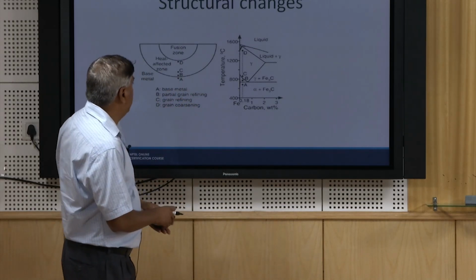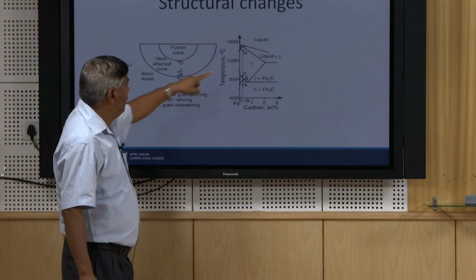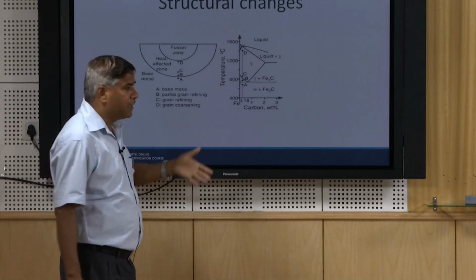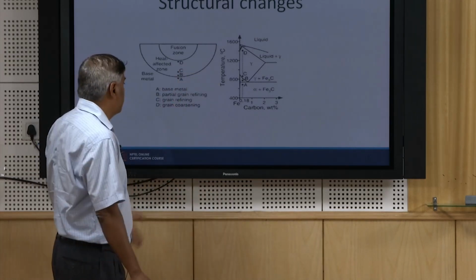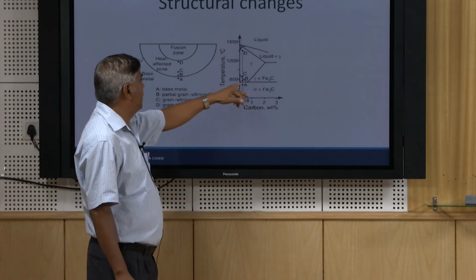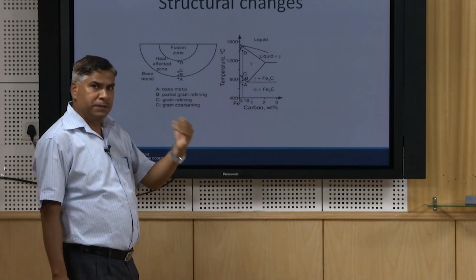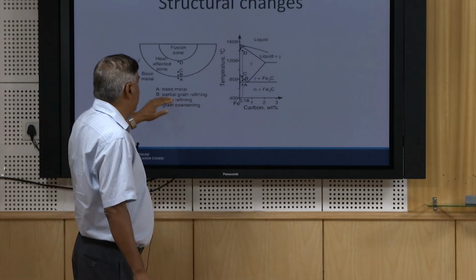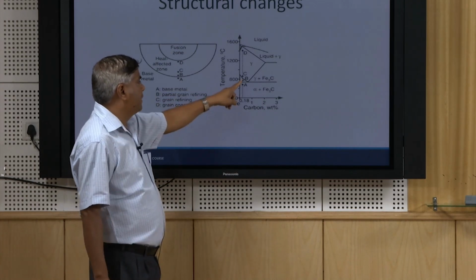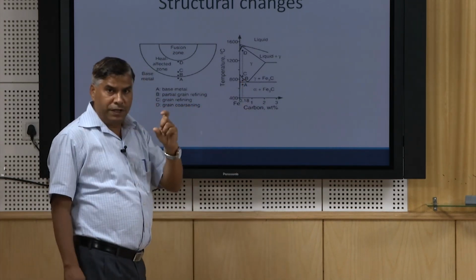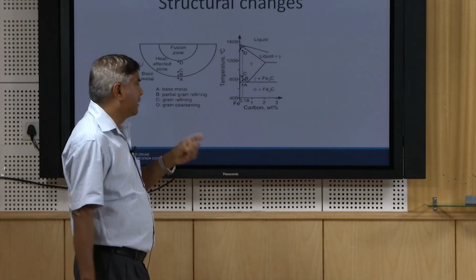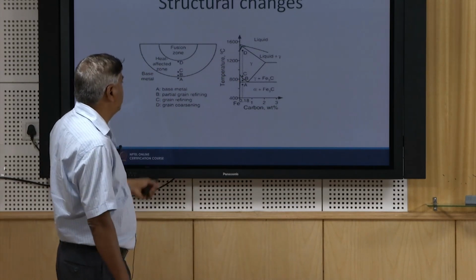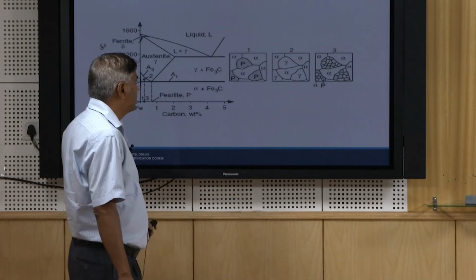So, accordingly, point D will be experiencing grain coarsening in the form of austenite, and subsequent rapid cooling results in coarse martensite. C will be experiencing fine grain refinement, and this will result in fine pearlite. A partially refined zone will be experienced by point B, which is in the two-phase zone. Basically, it is the intercritical zone falling between the upper critical and the lower critical temperature lines, and the base metal is A.